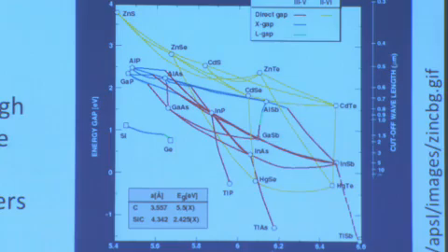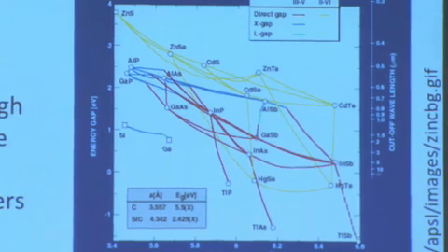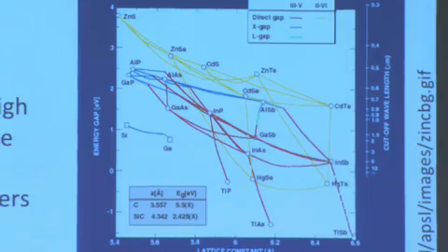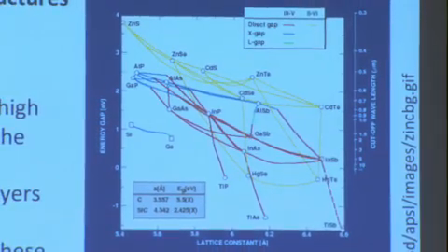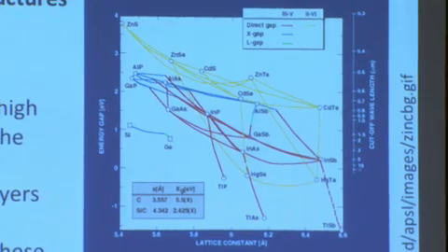They have 3 different band gaps. They absorb in 3 different regions of the solar spectrum, but they have a very similar lattice constant. And so the interfaces will be very well maintained. That's an example of using a chart like this to design your solar cell materials.